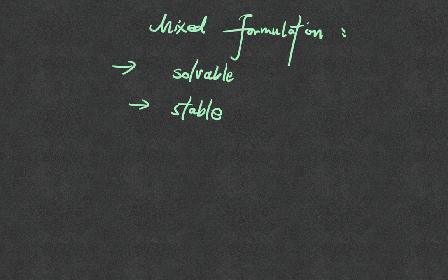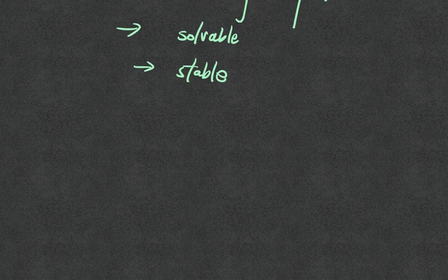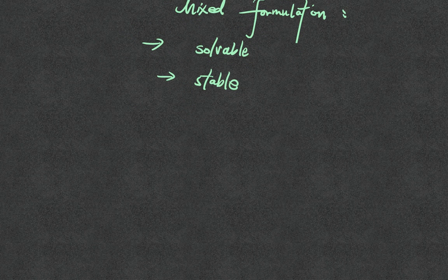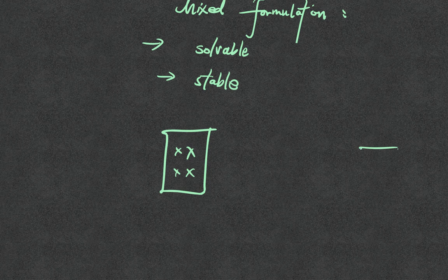Have you guys tried that? Do you know what I mean by reduced order integration? Maybe I can explain it a little bit here before the break. So this is a quad element that has 4 Gauss points. What that means is that I have an integral I want to compute, and then let's say there's a length scale.